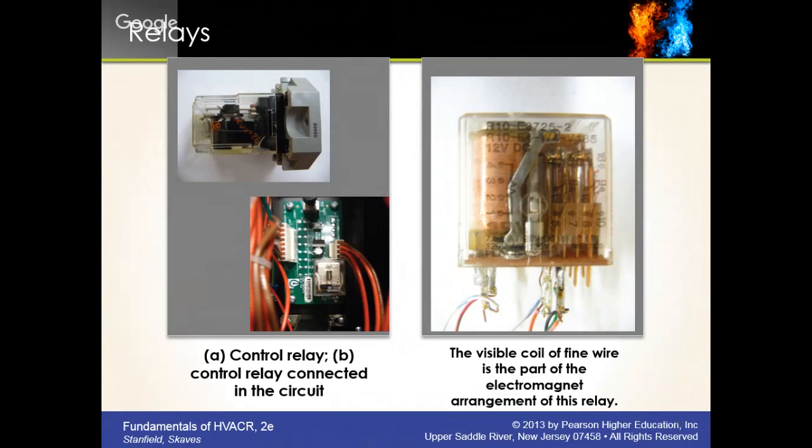Yeah, it could be. Or it could even be in line with like a pressure switch, something that's not going to have a load on it. That is basically where you're going to see a relay. Their terminals are smaller. We all looked at the terminals; they're much smaller than the contactor, and we can just know by looking that it's not going to take a huge amount of current to pull that thing out of the water. So they're typically used on the switching side of things, especially the little ice cube relays that we handed out. That's the big difference between the two.